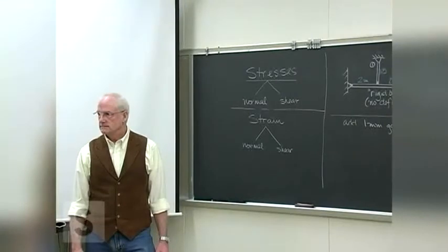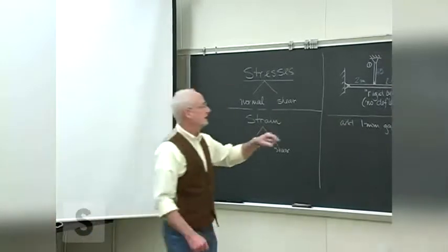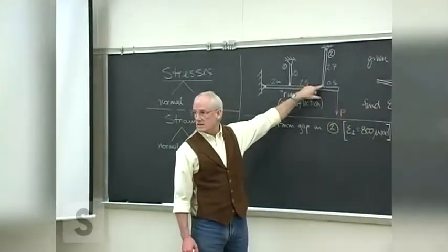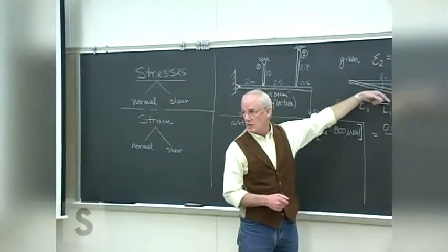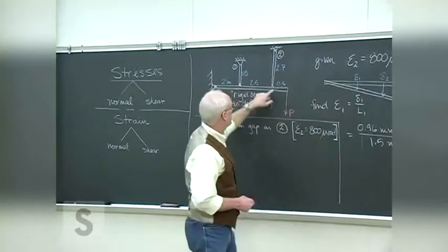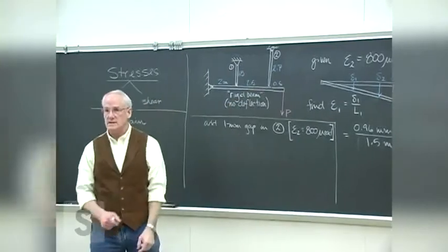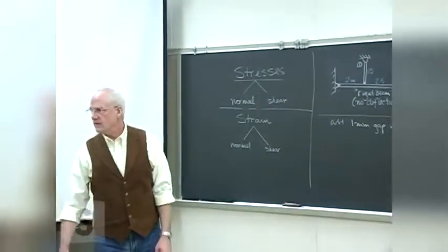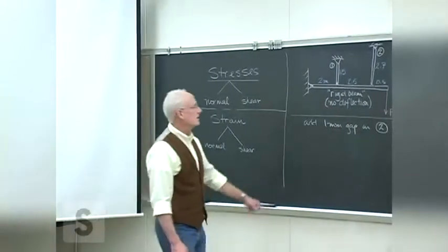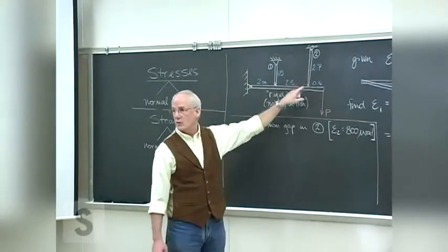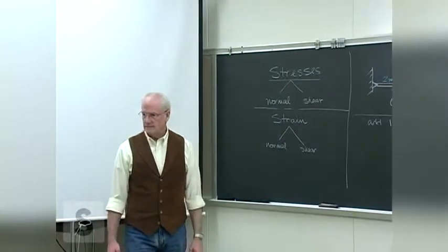What does that mean? I can move a millimeter before it's... Yeah, there's a little bit of slop in the pin connection, such that as this load causes the beam to rotate a little bit, it'll move a millimeter at this connection before there's even full contact in the piece. Just manufacturing tolerances, or possibly a certain size pin was planned for but not actually available, or a combination of both.